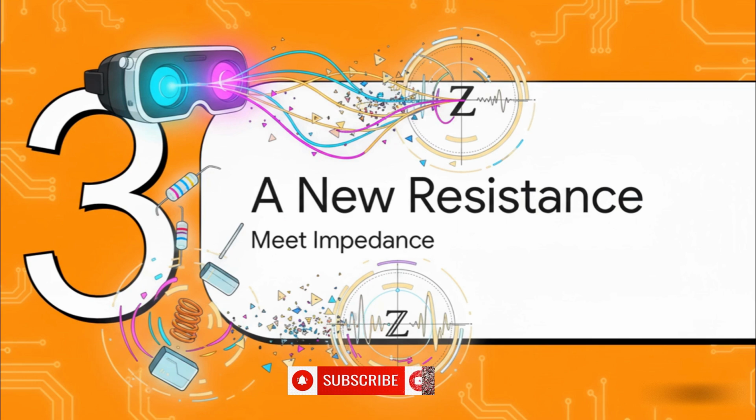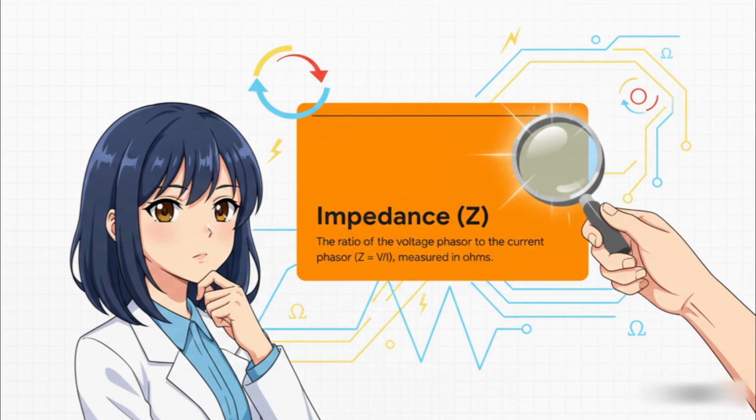Okay, so we've got our goggles on, and the world looks a little different. Resistors, capacitors, inductors, they don't quite look the same anymore. Instead, we see this new, unified concept that rules everything. So let's meet impedance. Impedance, which we write with a Z, is basically the frequency domain's version of resistance. Remember Ohm's law? R equals V over I? Well, impedance is just the voltage phasor divided by the current phasor. And yet, you guessed it, it's also measured in ohms, which should make it feel a little bit more familiar.